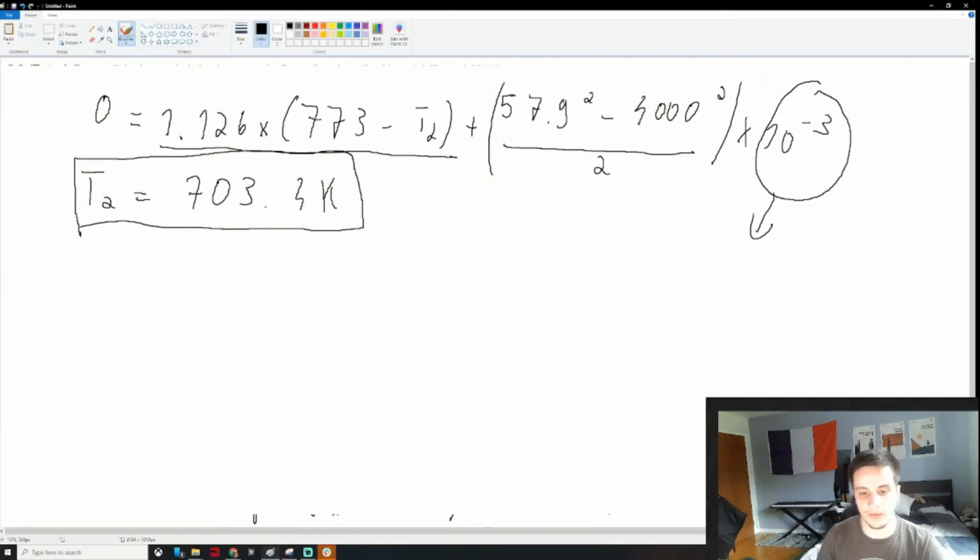Those are the two biggest errors: forgetting to convert from joules to kilojoules or kilojoules to joules, and making sure you have everything in the right order. So either it's velocity at the exit minus velocity at the entrance, or the other way around. That's not just for velocities, that's also for temperatures, just like how you saw me hesitating there. Same thing for maybe the change in altitude. Those are the two big traps you could get for this chapter.